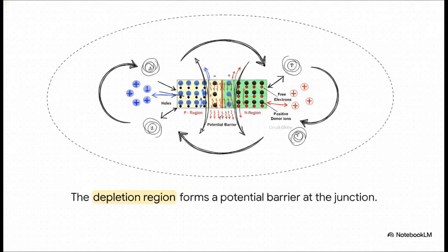To truly get why a diode acts the way it does, we have to anchor ourselves in the physical reality of the PN junction itself. Imagine joining a P-type and an N-type semiconductor together. Instantly, electrons and holes start diffusing across the gap. But notice that zone right in the middle? That's the depletion region. It's basically wiped completely clean of mobile charge carriers, leaving behind these immobile ions that set up a built-in electric field. It's literally a potential barrier. For electrons and holes to cross and actually create a current, they have to somehow climb over that wall.